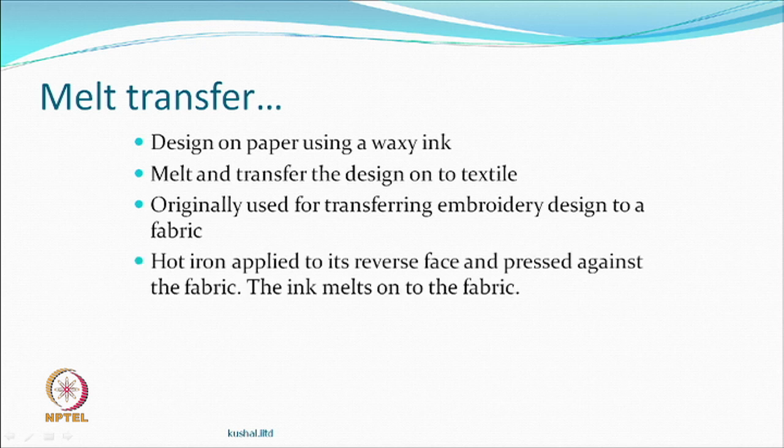So, wherever you do certain things, here also whatever is in the film that is going to melt and get transferred will get transferred irrespective of whether it likes the fiber or does not like the fiber. You see, in the first cases the dispersed dye liked the fiber. In the wet transfer you also wanted fiber and dye to like each other. In this case you are saying it is just the molten material that is going there and going to get stuck. It has got color and design. So, do not worry about it, whatever happens will be there.